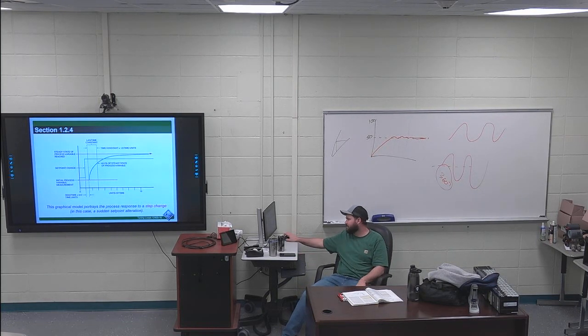I'm pretty sure those are Honeywell brand out there, but this is just a little bit older version of that. This is kind of the equation that I was showing you, like 63.2%. That's your lag time or your time constant. So that's kind of how long it takes to get to steady state. So time constant of 1.5.